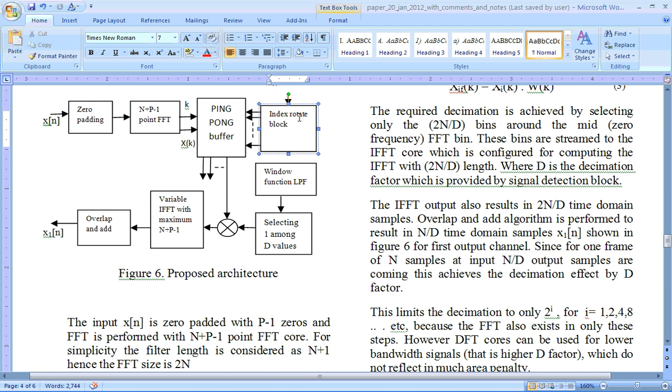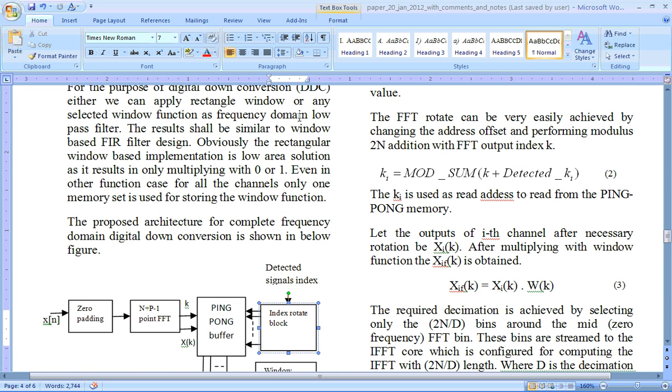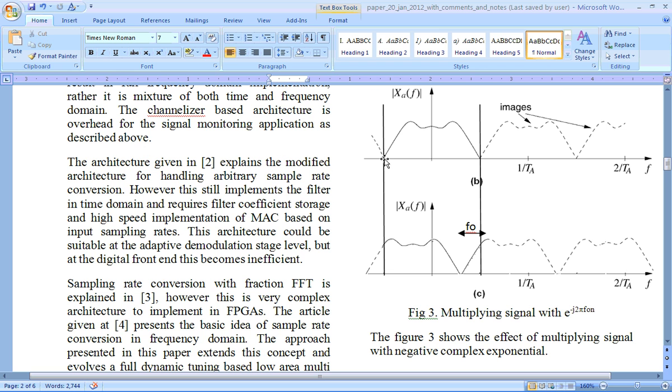So what happens now? Look at this diagram. This is actually address 0. Now here somewhere you have address 100, and you want to achieve rotation by 100. So what is done is, the normal counter which starts from 0, you always add 100 and that is the address. So automatically this sample comes first. Isn't it? This sample comes first, and once you reach 1024, because we use only a 10 bit value, the counter will overflow and then the counter becomes 0.